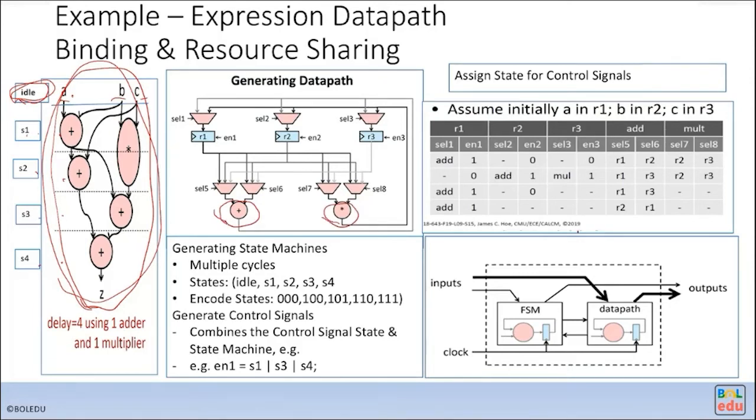For each adder, you will need to decide the state variables. State variables become your registers, and then there are your operators. For each state variable, you have multiple inputs, so you have a mux select.